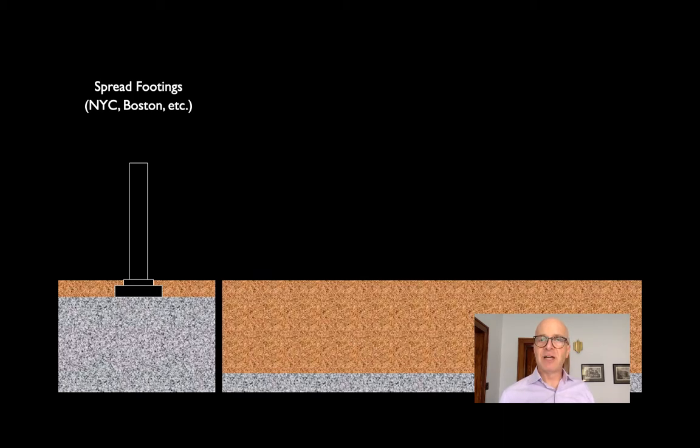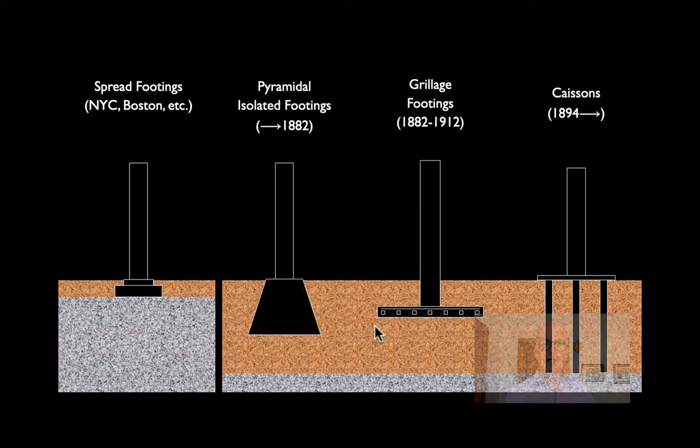In cities like Philadelphia and Chicago, river cities especially, it was a very different condition. Chicago downtown has about 80 feet of basically fluid soil, clay, hard pan down 20 feet or so, but fairly weak soil. And so what happened in Chicago is they realized that they essentially had to float the buildings.